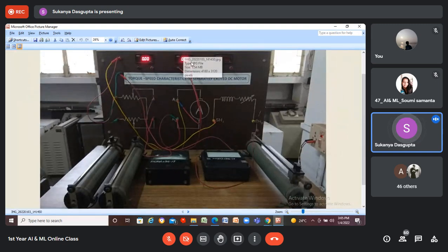This is the digital type voltmeter, which is used to measure the armature voltage or the applied voltage in the data table. And these two are ammeters, table mounted analog DC meters. DC meters means definitely moving coil type meters. Moving coil ammeters will measure the DC current only.